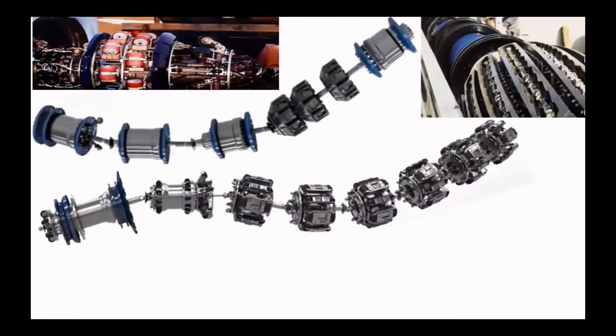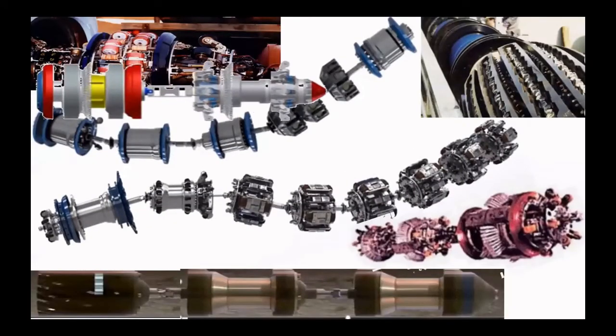Let's go to the second step. In this part, you need to select the correct inline inspection tool. There are a lot of inline inspection tools available: MFL, circumferential MFL, ultrasonic compression wave, ultrasonic shear wave, EMAT, elastic wave, eddy current, you name it. But which tool gives you the biggest bang for the buck? Which is the best tool for your inline inspection requirements?